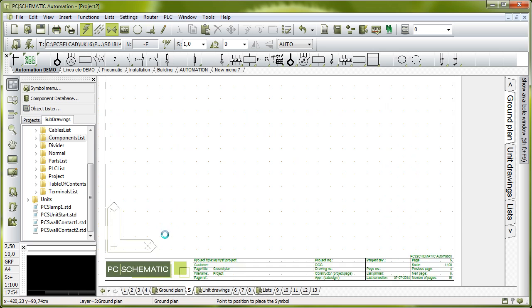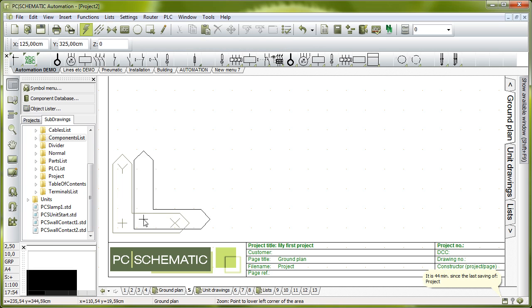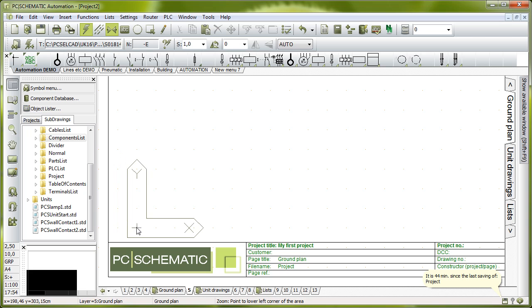When I make this drawing here, I use this Origo or 0.0 in the coordinate system. I want to have it on the corner of the house, and I will also want to make use of all those small dots. I can move my Origo by clicking this icon here, and then I can place it directly on one of the dots. That makes it easier for me when I'm just looking through my drawing.